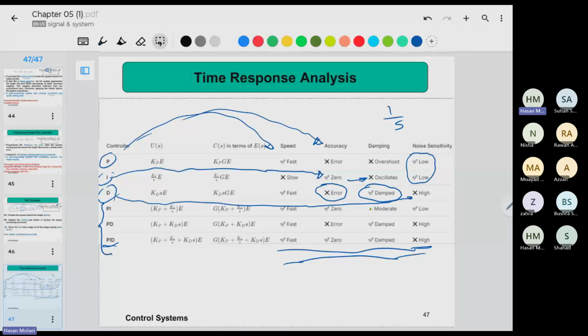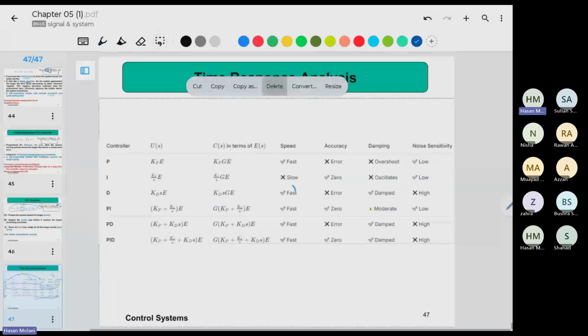But if you make it faster, the problem is that when we reduce rise time, we had overshoot. Sometimes our system cannot have overshoot. For example, pressing acceleration, you go fast and suddenly, when your stepper has a problem, it's going to shake. So you need something to reduce the overshoot when you are increasing your speed.